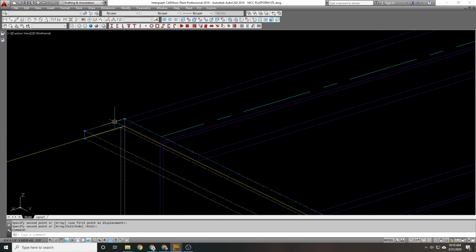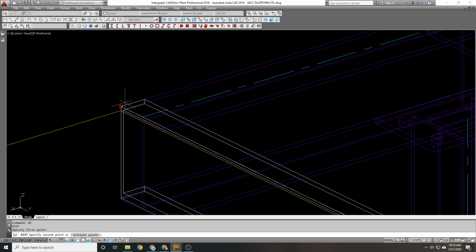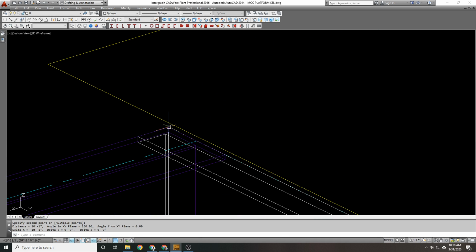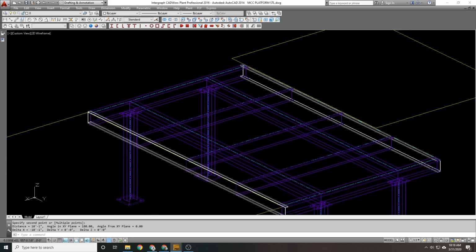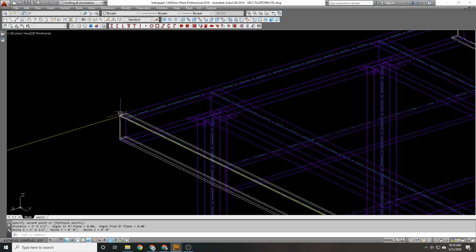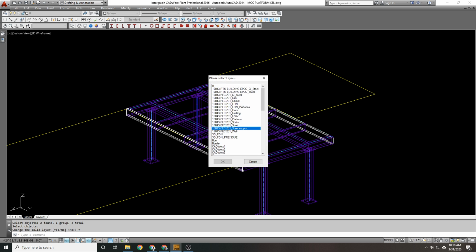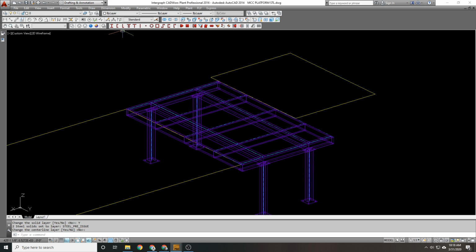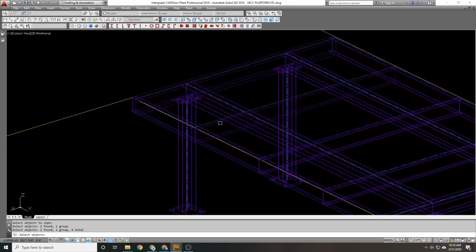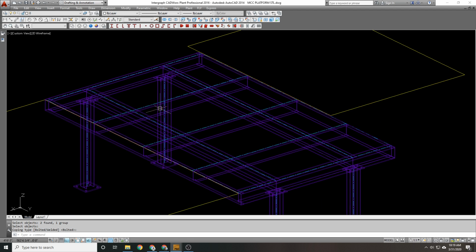I can copy this to here and then just do this flip flange and it puts it back to that direction. Let me measure this platform actually. Yeah, 10'1". That means it's symmetrical. So from here to here should be something 1/2 inch at 2'6.5". Okay. So do my S layer change, S layer change. Okay. And there we are. I'm going to make sure to cope this on this side. Bolted.